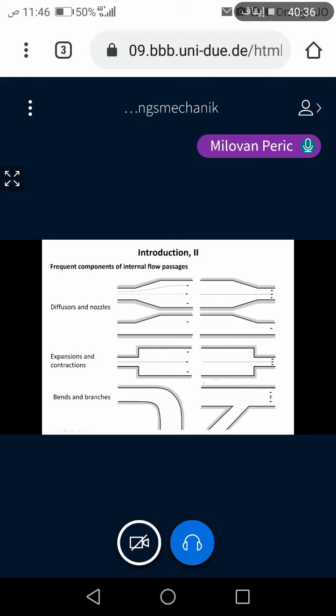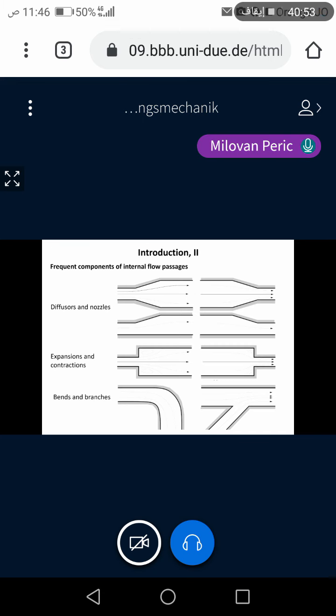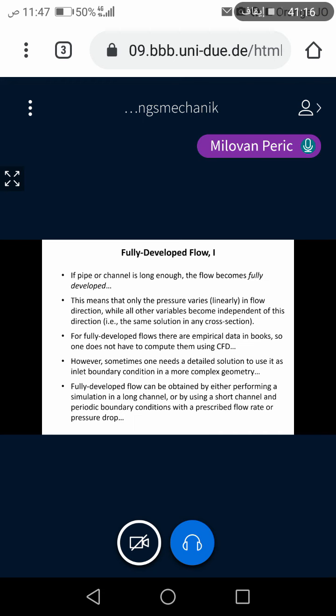So these are the things that we are concerned about, and these are usually ones that need to be simulated, because you can do, of course, measurements, but then doing measurements for building models for every one of these is a little bit complicated. Now there is a book I forgot to mention earlier by Idelchik, that was a Russian scientist who has a thick, big book which has information about local losses at very many different configurations. So if somebody needs to look for these, then Idelchik, if you remember the name.